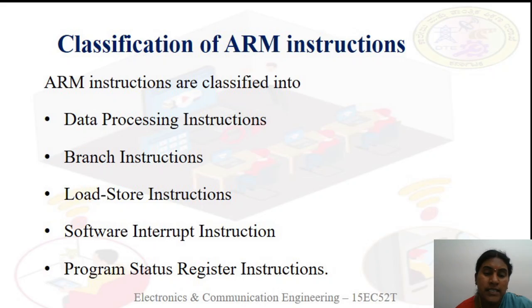MSR is used to copy the content of a register into the CPSR or SPSR, and MRS is mainly used to copy the content of the SPSR or CPSR to the registers. These are the main classifications that we find in an ARM processor.